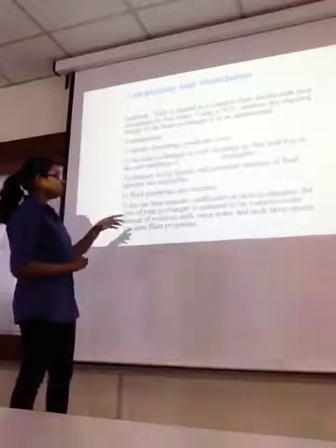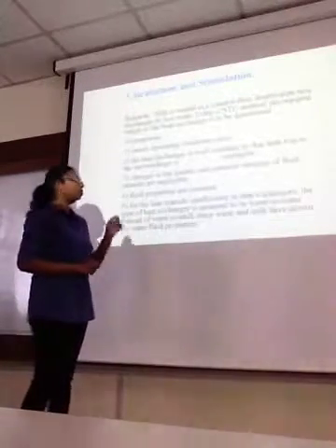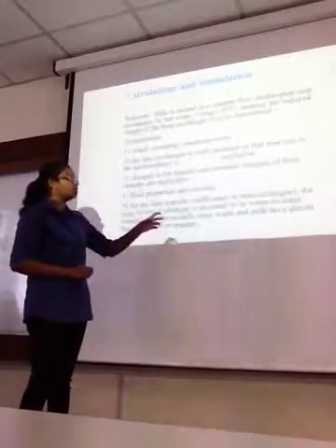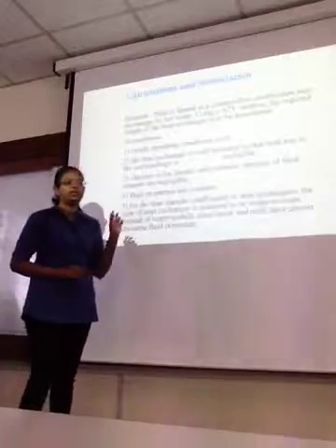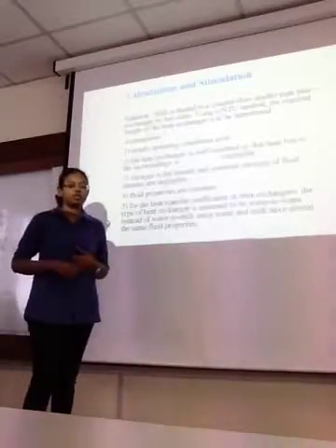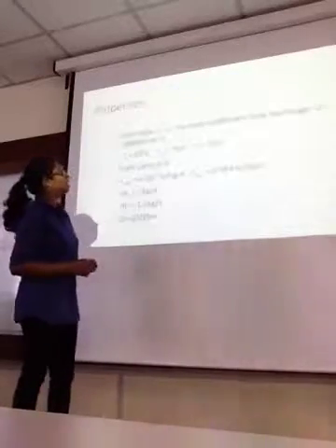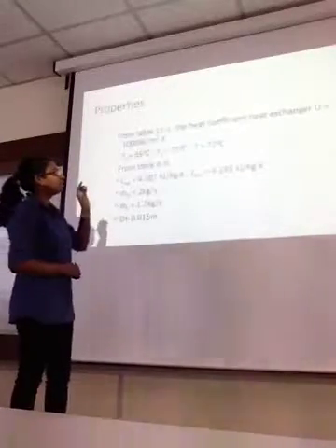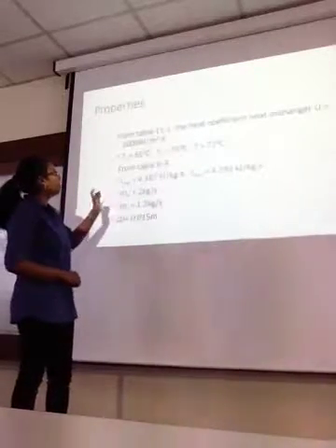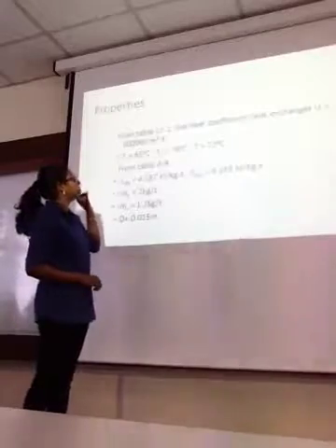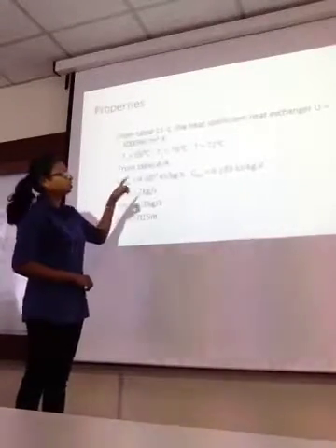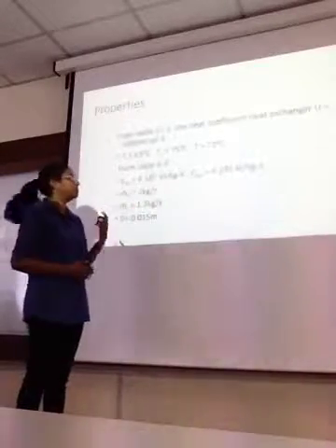For the heat transfer coefficient, we assumed that the value is the same as water to water instead of water to milk, because we assume that milk has almost the same properties as water. From the table we can take the heat exchanger coefficient, the U value. Then we assumed that the inlet temperature will be 65 and the outlet temperature will be 75 and the system temperature will be 72.